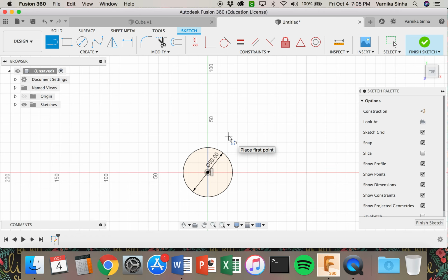Now, we have the sketch mirrored on both sides, which isn't good. Think about revolving at 360 degrees. You have it on both sides. You should only have the image on one side of the axis, not the other side. This is going to be a bad idea. So how do we get rid of the extra side on the other side of the axis?